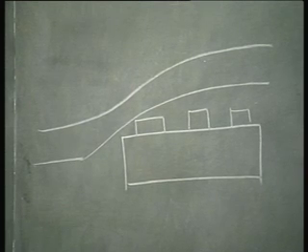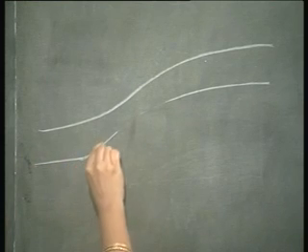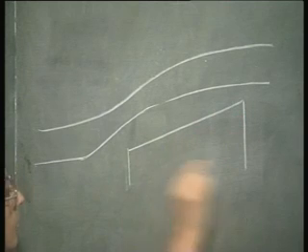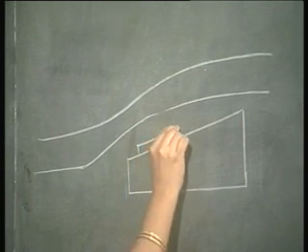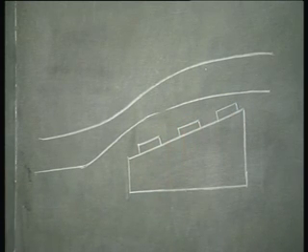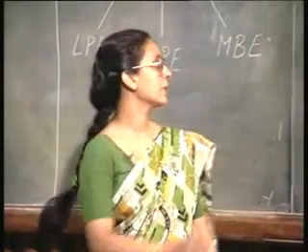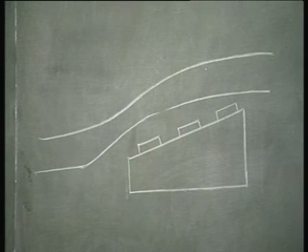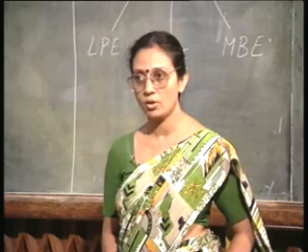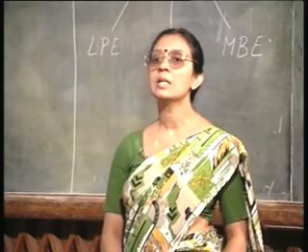Now, let me change the sample holder design like this. I have a tilted sample holder. The top surface is an inclined plane and the samples are kept like this, so that as you go down the length of the tube, the samples are placed higher, so that the effective width of the stagnant layer remains more or less the same, so as to ensure equal growth rate for all the samples. Particularly when the gas flow is parallel to the sample surface, that is in these reactors which are called the horizontal reactors, this is almost universally the sample holder design that is accepted in order to reduce the boundary layer problem. That is, you have an inclined sample holder.